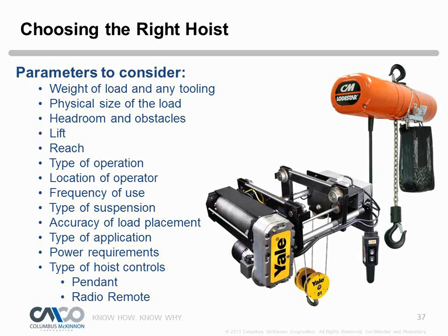Here we got a question that came in. Sure. Cable hoists are meant for faster speeds. Is that correct? Generally, you'll see wire rope hoists at faster speeds, given that the chain hoist, in the higher capacities, is going to be multiple reeved, and so we have to overhaul all that chain. So typically, in the larger capacities, you're going to see wire rope. If you do side by sides with wire rope models, you'll see some faster speeds in the wire rope hoist.